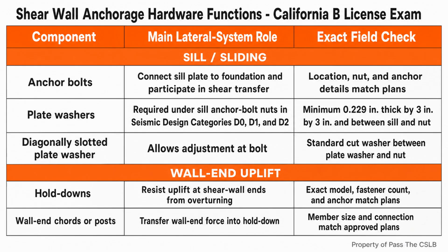I verify every horizontal and vertical edge has framing or solid blocking. I compare the fastener type and pattern to the schedule, paying special attention to boundary edges, panel joints, top and bottom plates, and any tight spacing that requires staggered rows. Then I look at the framing behind the fasteners. I check for split studs, missed framing, and unauthorized substitutions. At high shear joints, I confirm the required wider member or approved double member assembly.